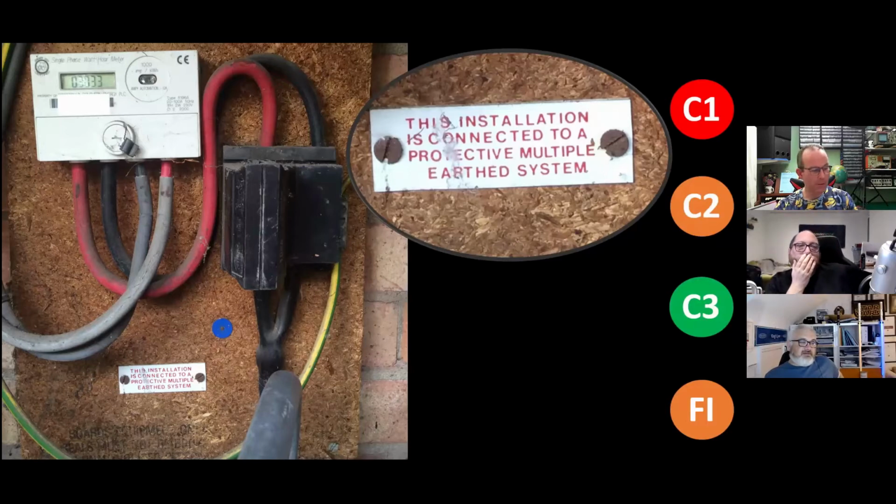See, for me, I would FI the cutout. I would ring the DNO and say, are you still happy for these to be used? And then the duty's passed on to them. And I'd probably see to the tails, just if it's in a home and there's children present and all the rest of it and it's accessible. Yeah, David needs a little bit of TLC.